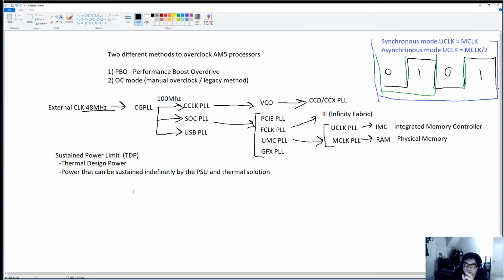The difference is the tau value, the time value on the motherboard, will tell the processor to thermal throttle after a certain amount of time. So it runs, heats up, then slows down. That tau value determines how long it can cook itself. It is a user-provisional value, but I do think there are some knobs the motherboard manufacturer will put in for reliability reasons, to prevent the processor from killing itself. But that is different from AMD, where AMD defines their TDP as a sustained power limit.